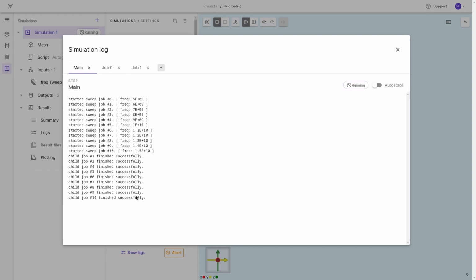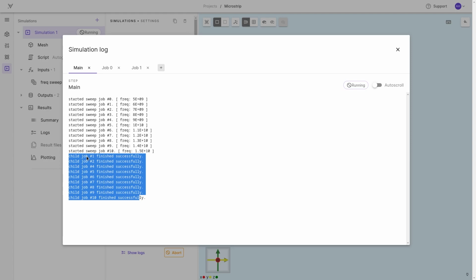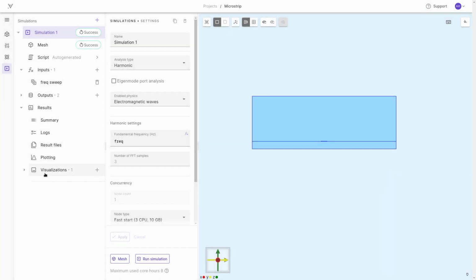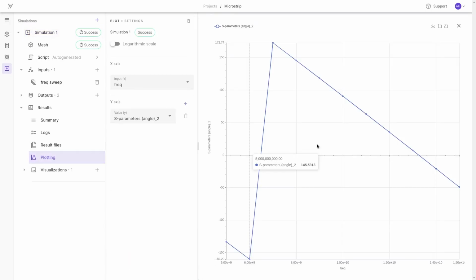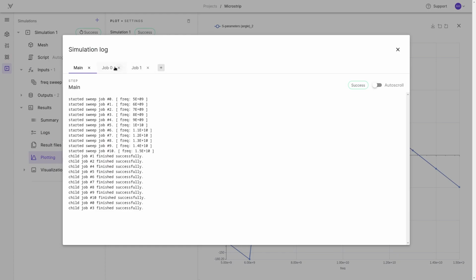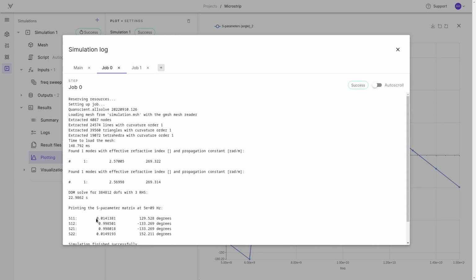And most of the jobs have finished. We're still waiting for 2 more. So these are finished too now. And we can again plot. This hasn't probably changed much, but what has probably changed more is this artificial reflection. So now you had 5%, now we have around 1.4%. So this is really low reflection. So that is probably around minus 35 dBs or something like this.